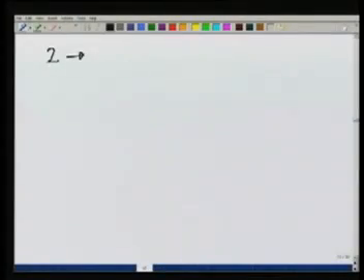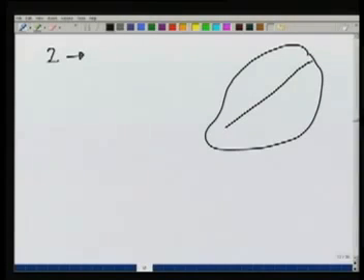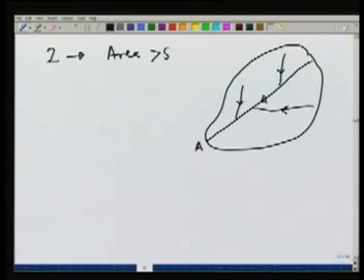Now the second problem which we will look at is if we have an area which is quite large. Now there may be a river which is joined by a number of tributaries, and this area being very large, let's say more than 5,000 kilometers square, we will not be able to use the unit hydrograph to predict the direct runoff at A due to any storm occurring over this area, because typically for a larger area the assumptions made in the unit hydrograph theory will not be valid.